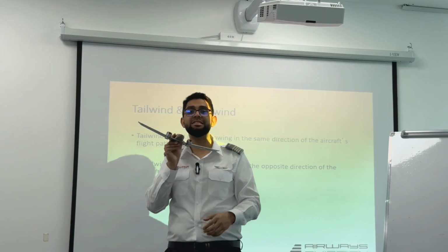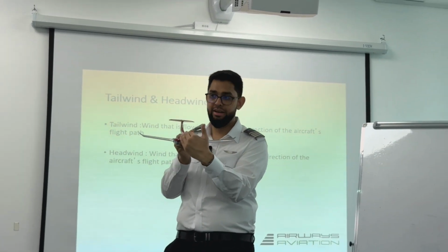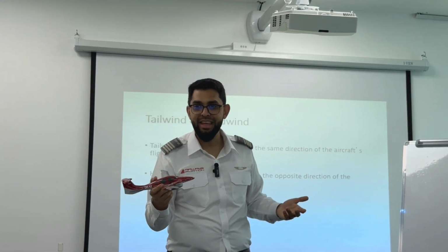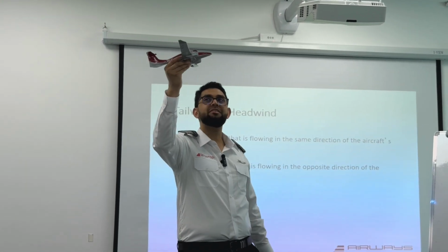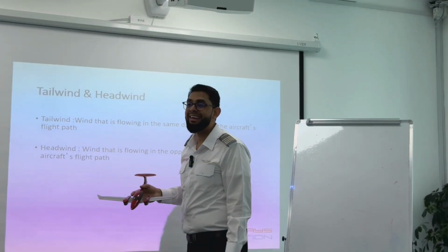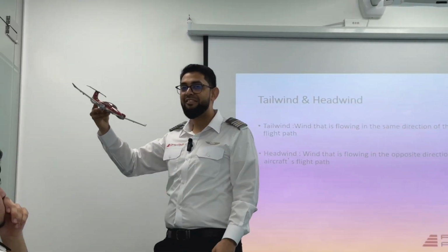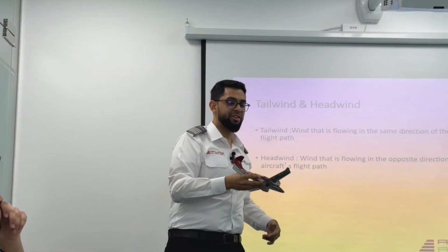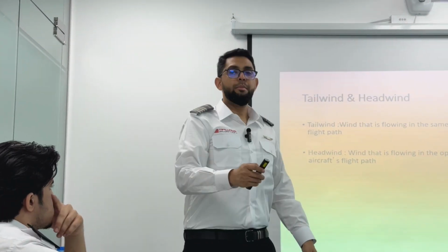You have to always land into the wind with a headwind, because that's when the air goes faster above, slower below, creates lift, right? So when you're flying up at the cruise level, sure, headwinds will make you reach your destinations faster. But when you are taking off or landing, you have to take off into the wind and you have to land into the wind. Please remember that. We'll obviously talk about them in more detail when we start talking about principles of flight.